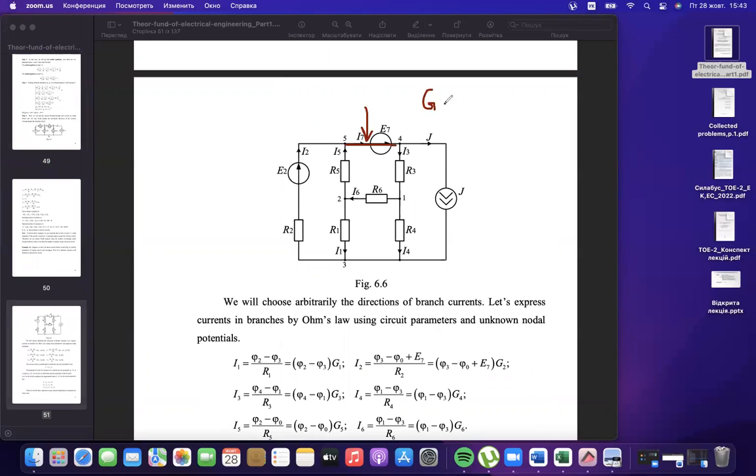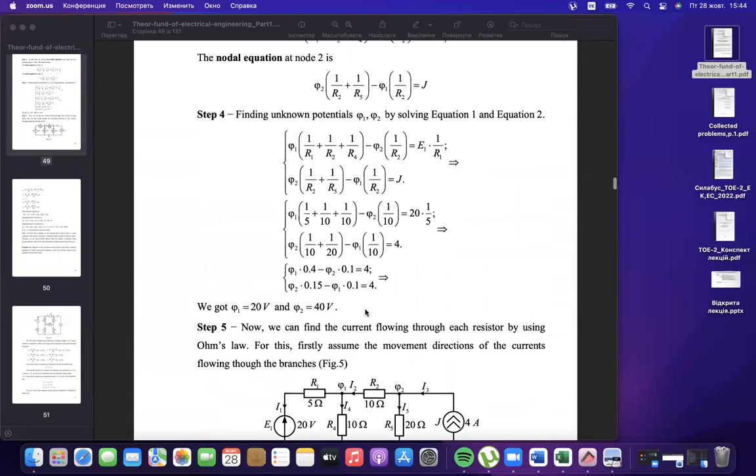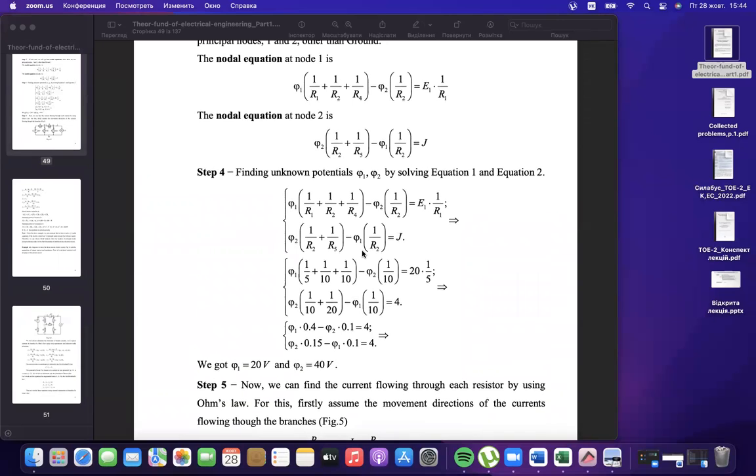The conductivity should equal 1 over resistivity, but in this case the resistivity is only that of the electromotive force, which is almost 0 because it has a very small internal resistance. Then you are dividing by 0 and obtain an infinitely high conductivity for this branch. And if you substitute an infinitely high value inside the equation, you cannot solve it.